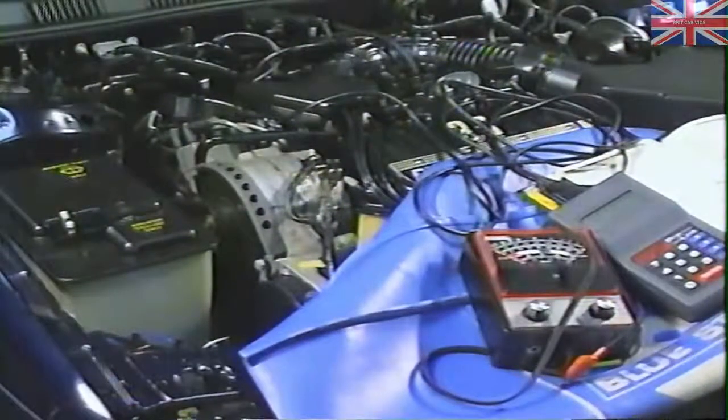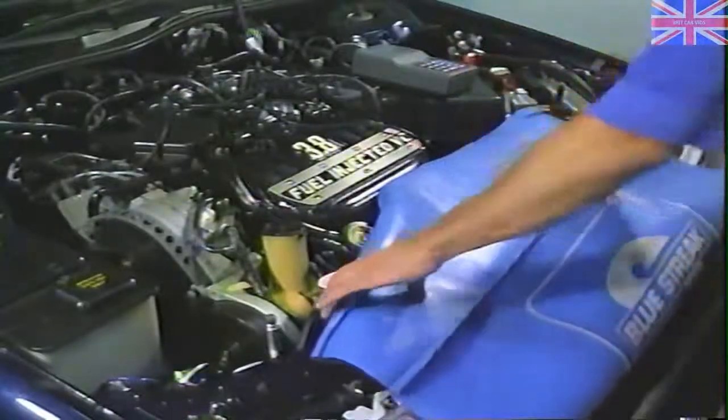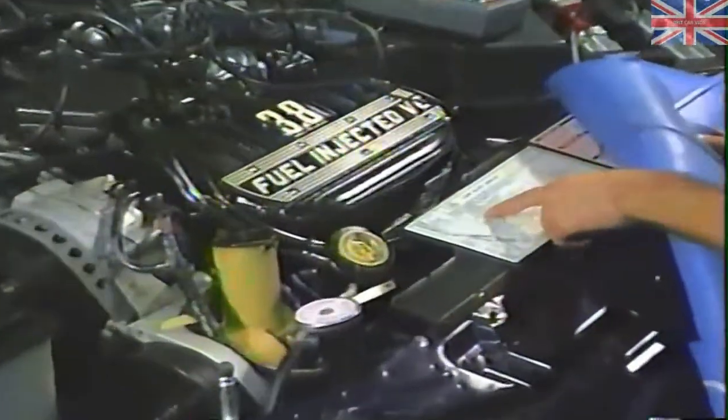Since we know we have a problem and we do not have any on-demand codes, the next test will be a timing check. This will verify that the EEC assembly is properly advancing the ignition timing. Ford states if the base timing is 10 degrees before top dead center, self-test timing should be equal to 10 degrees fixed timing plus 20 degrees computer advance for a 30-degree total. For the exact base timing specifications, you should check the Vehicle Emissions Control Identification decal that's located in the engine